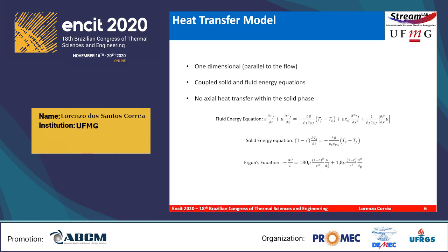This way, the fluid energy equation stands as this first equation shown here, with the first item being related to the change of energy inside a volume in time, and the second is related to the energy that crosses the volume borders. The third represents the convection heat exchange with the solid phase, and thus this justified the coupled equations. The fourth represents the advection and diffusion of the heat within the fluid, and the fifth is the heat generated by the viscous friction.